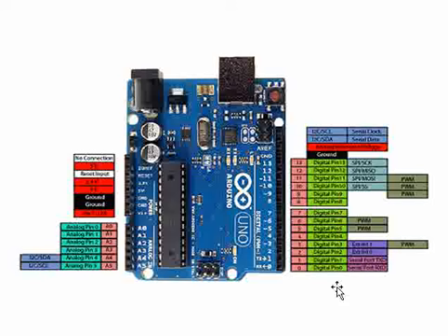And then on the right, these are the digital pins that are connected, and you have I2C connections, and it supports PWM as well. And then SPI connectivity is there, and you have the interrupts here, external interrupt 0, external interrupt 1, and you have the UART pins, basically the TX and RX pins. So this gives a glimpse of the alternate functions of each and every pin, and then we will talk more about each and every functionality.